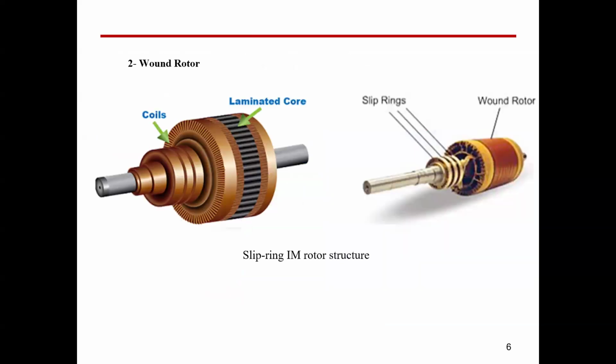Here is the other shape. So the other shape is still with the same core, but we have external slots. And these slots are used to have the windings on the outer slots of the machine. But the induction machine is a three-phase machine, so we have three-phase windings for the rotor. And you know, the rotor is a rotating part, a moving part.